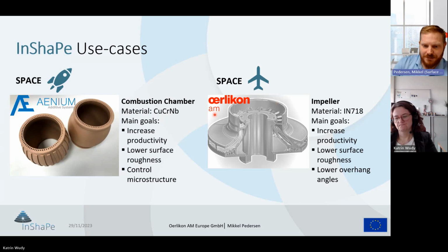Of course, as a pump system, we have internal surfaces that otherwise need polishing. So the better we can print these surfaces, the less we have the post-process. And of course, the, let's say, traditional support structure is a topic to avoid inside these channels because it's a challenge to get out. And of course, also a point where we print material that is essentially wasted, so creating scrap from this process as well. If we go to the next slide.